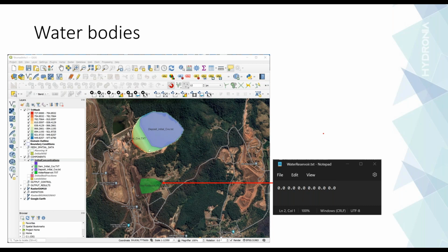So when the concentration of the material falls below approximately 15%, then the rheological formulation used for those low concentrations, which can be zero, will be those of turbulent flow, while those for the high concentration fluid will be the rheological formulations that you have selected, let's say the Coulomb formulations or dry.